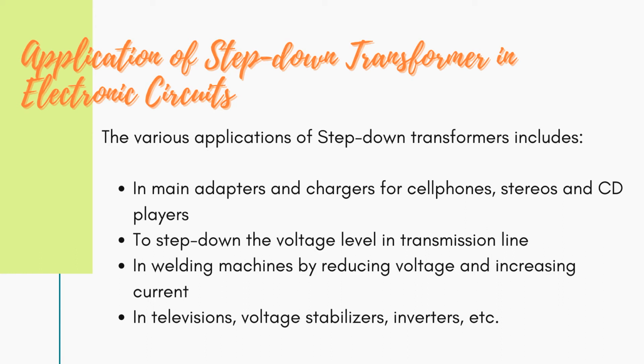Application of step-down transformer in electronic circuits. The various applications of step-down transformers include: 1. In mains adapters and chargers for cell phones, stereos and CD players. 2. To step down the voltage level in transmission lines. 3. In welding machines by reducing voltage and increasing current. 4. In televisions, voltage stabilizers, inverters, etc.